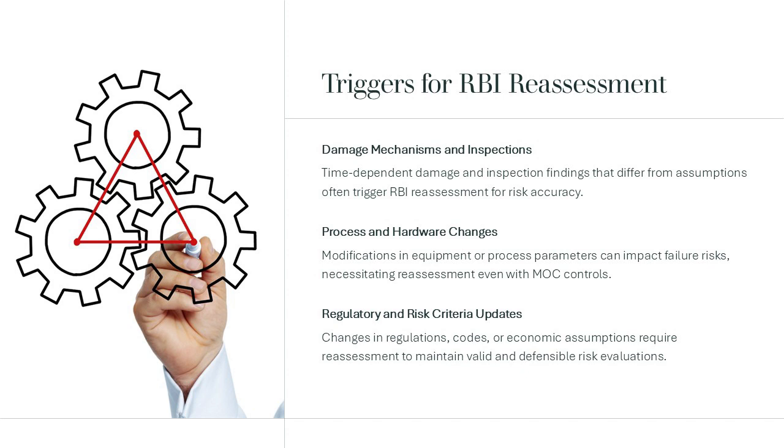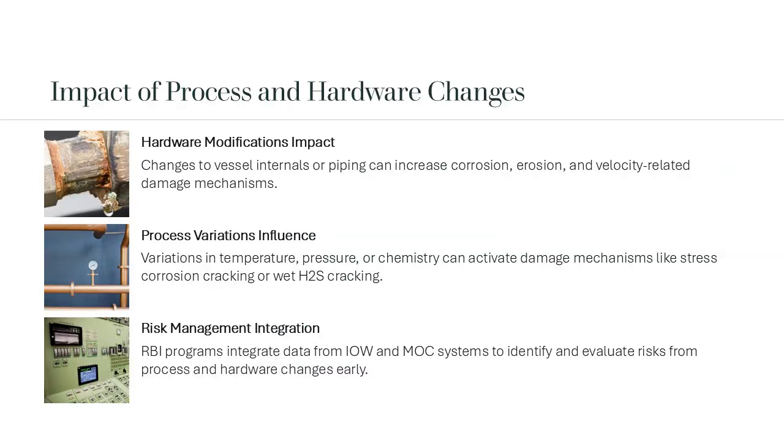Other triggers include changes in regulatory requirements, inspection codes, risk criteria, or economic assumptions. When the foundational premises of the RBI assessment change, reassessment ensures that risk evaluations remain valid and defensible. Process and hardware changes can significantly influence both the probability and consequence of failure.